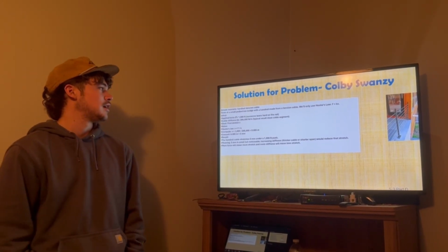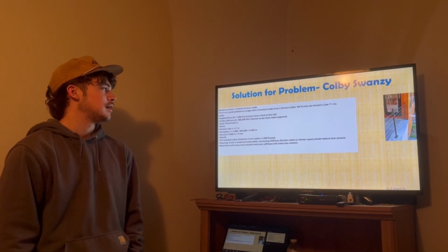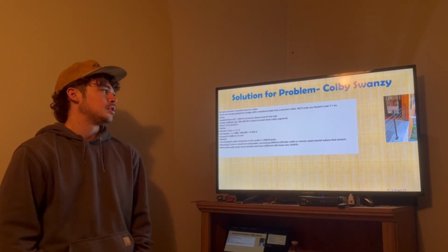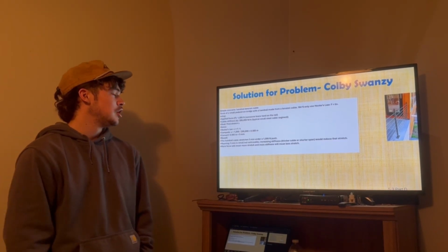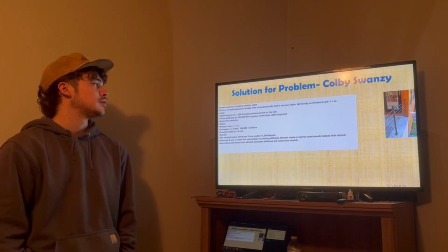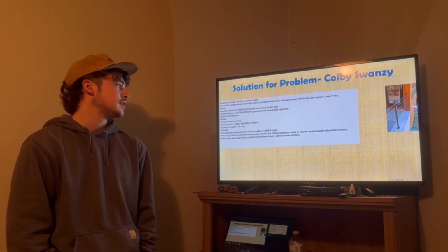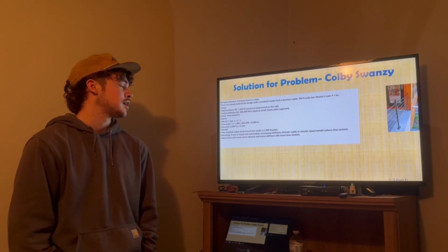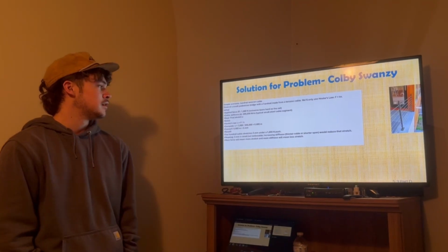Simple scenario: handrail tension cable. Think of a small pedestrian bridge with a handrail made from a tension cable. We will only use Hooke's law, F equals Kx. The setup is applied force, 1,000 N, someone leans hard on the rail. Cable stiffness, 200,000 N/m, a typical small steel cable segment. The goal is to find the stretch, X.